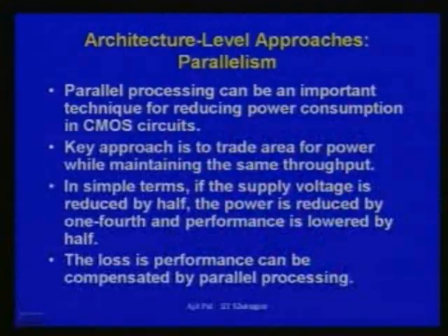But if we keep the performance the same, then power dissipation can be reduced. I shall explain how it can be done. The basic idea is this: we are trading area for power. We are increasing the area, but power dissipation is reduced.